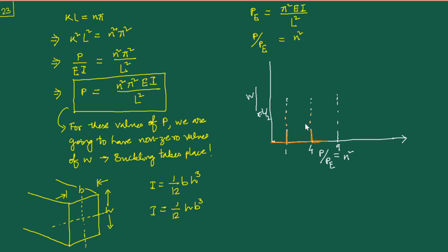So there is room for improvement in this theory also, even though it has managed to improve on the previous theory that we were talking about, where the bending and the stretching were completely decoupled. This theory has made an improvement on that, and it has enabled us to predict buckling, or some kind of compression-induced bending, as an instability.